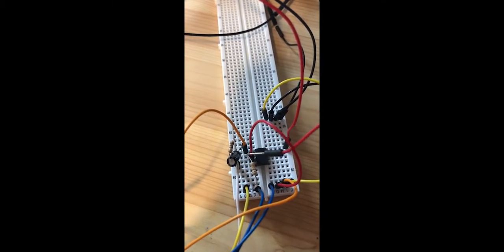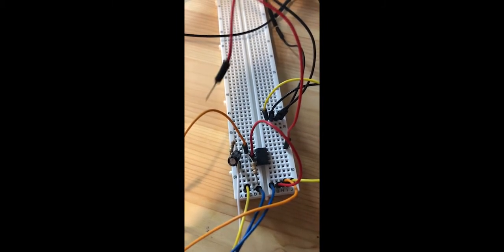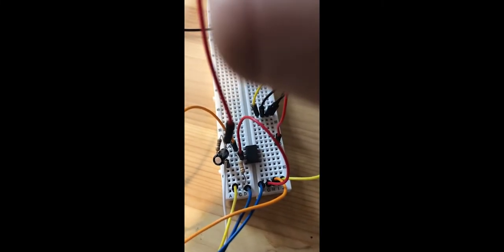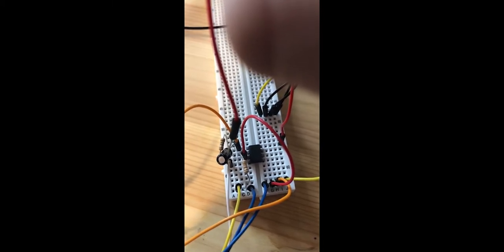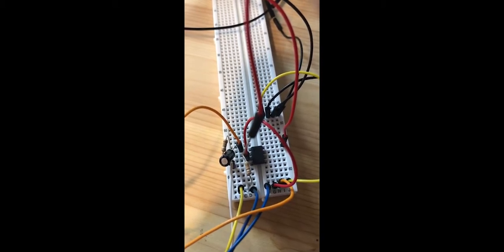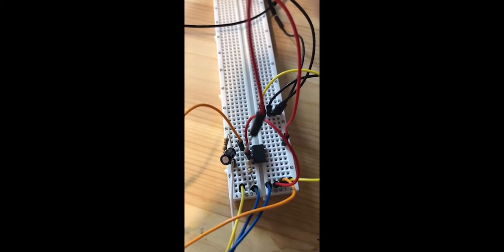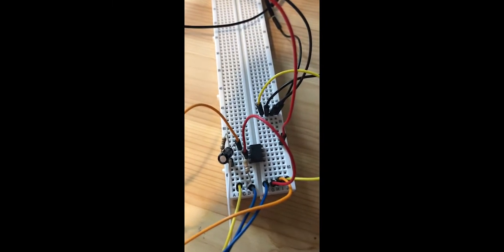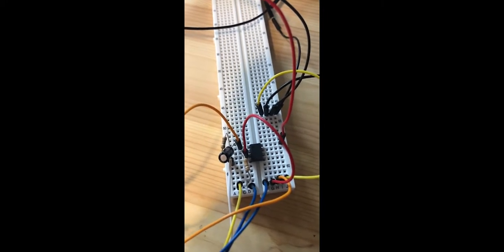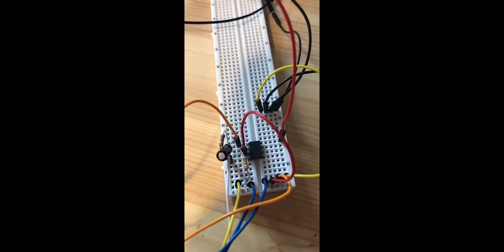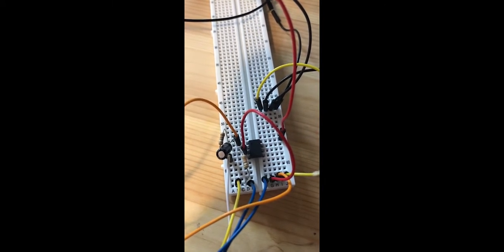According to the figure 1, we have a 1 mega ohm resistor, as you can see here, between pin 1 and 2, a 1 micro capacitor between pin 1 and 2, and there is a 10K resistor between pin 2 and the input. Input is the yellow line, the waveform generator from the analog discovery, and the white one, as I said, is the negative supply for the op-amp.